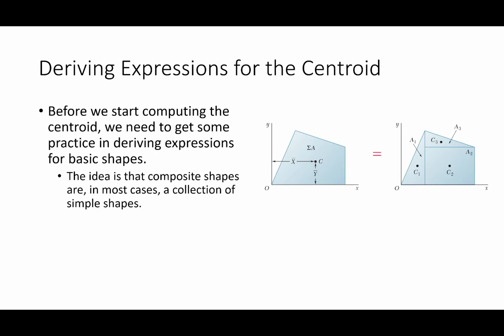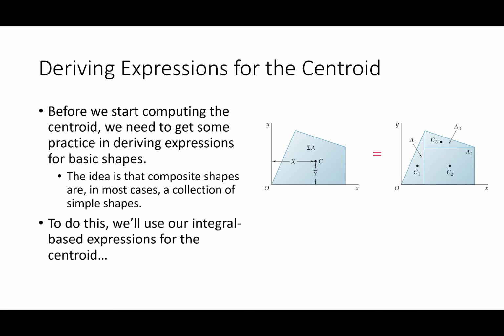Okay? A lot of times what we will do in practice is we will have problems like this. So I'll give you a plate like this and I'll say, okay, tell me where the centroid is. And in practice what we'll do is we'll take this plate and we'll break it up into a rectangle and a triangle and a triangle. And we can look up where the centroid of a triangle is, or the centroid of a semicircle, or something like that. We can look those up. And that's what we will do later. But for now, I want you to understand what those references are and what they look like.